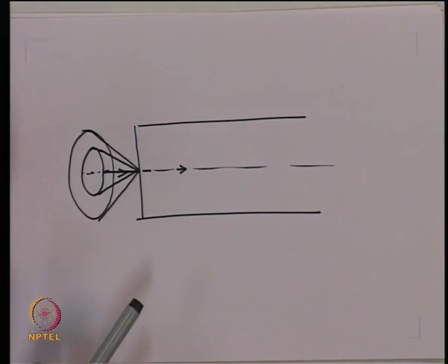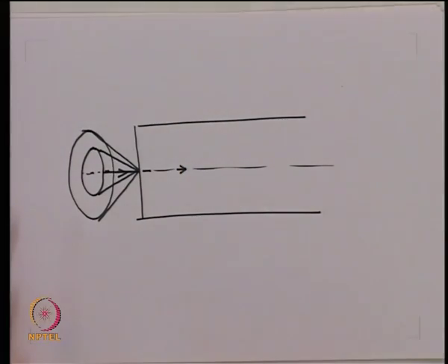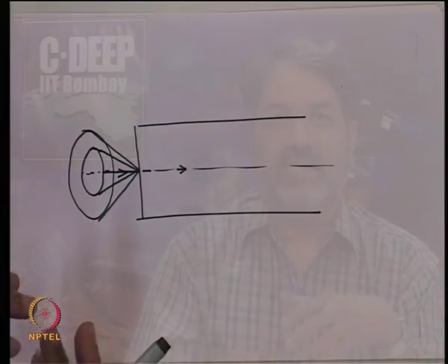So, now we see that even if you have a numerical aperture cone which is as large as this, the light launching efficiency is further reduced, because every ray which is lying within this cone cannot go inside the optical fiber. So, fiber chooses only light coming at those angles, and any other light essentially is rejected. So, the efficiency of launching inside the optical fiber is further restricted.